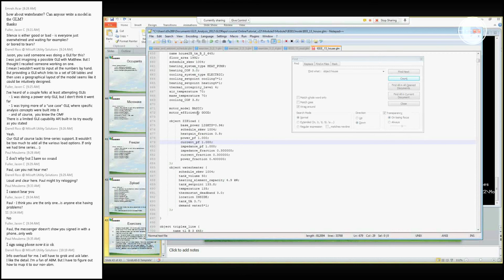And the only reason to add these pieces in there is because it turns out that with CVR, a lot of the value in CVR comes from the customer side of the meter, and a lot of that actually comes from the fact that motors are designed to operate typically at 110 to 115 volts as the design parameter, but most utilities are operating more like 120 to 125 volts. So you actually get a lot of efficiency by moving your voltage down into the motor's design voltage range. And this lets you capture that effect.